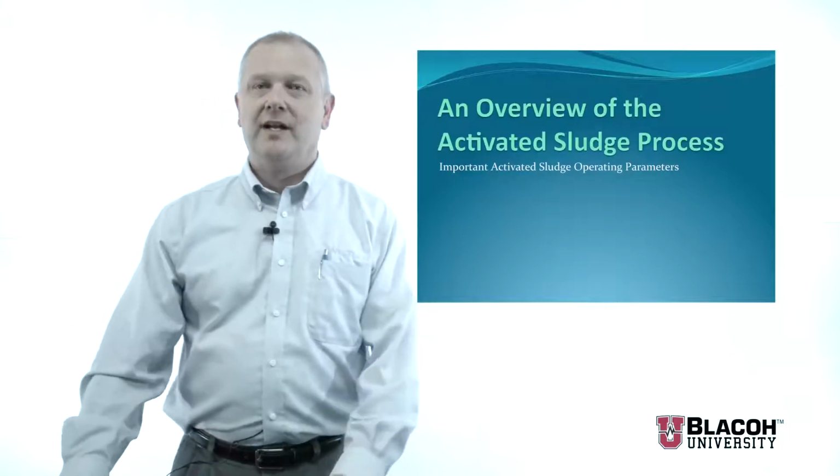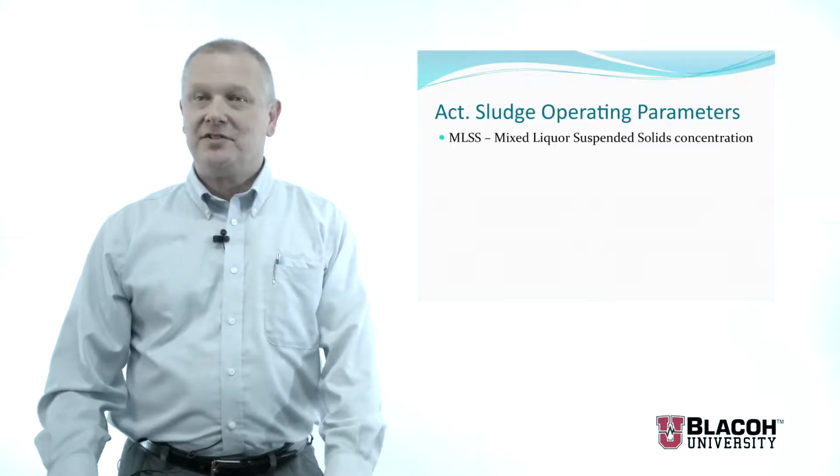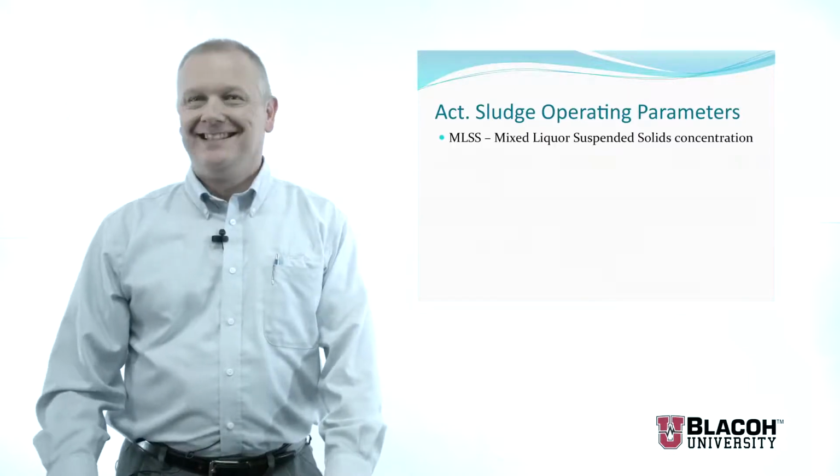Let's talk about some operating parameters in activated sludge. These are not terribly difficult systems to operate, but there's some important things that need to be watched so that the system performs properly. The first one we'll talk about is the mixed liquor suspended solids concentration.